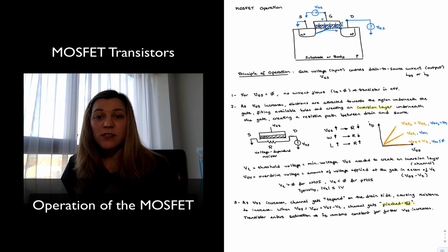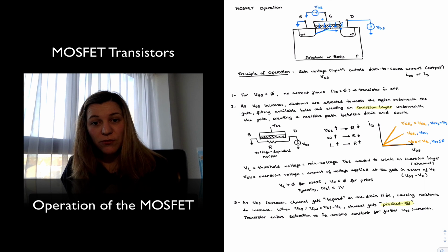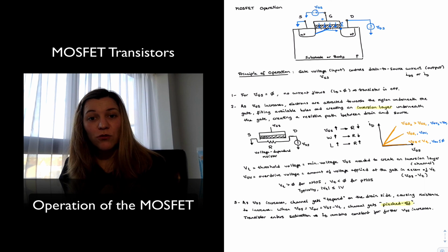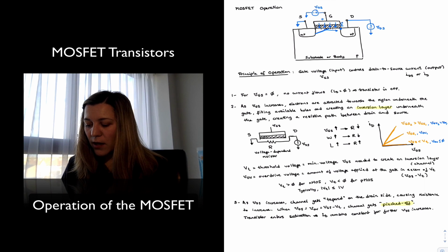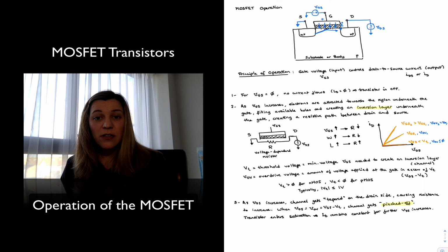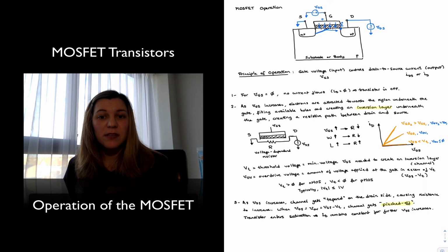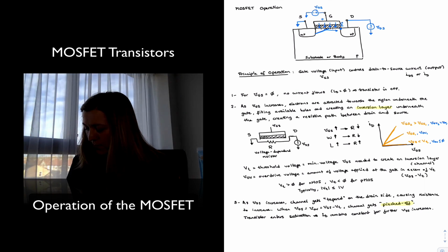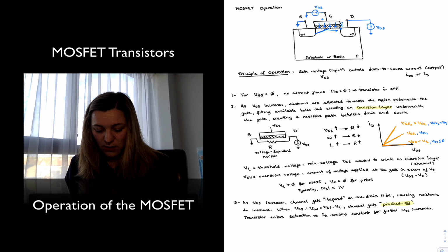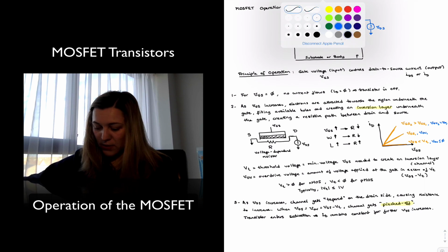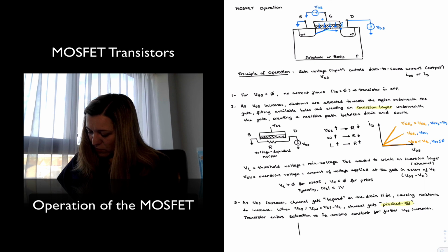And so the further increases are not due to a conductive path any longer, but rather these electrons are gaining enough kinetic energy to bridge that gap. As you keep increasing VDS, the channel keeps receding farther and farther, but the kinetic energy imparted to those electrons is higher. Both effects counteract each other, so the net effect is that the current remains approximately constant with further increases in VDS. And if I were to represent that graphically, what I will have is the following.